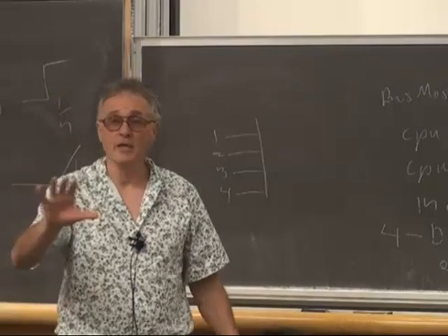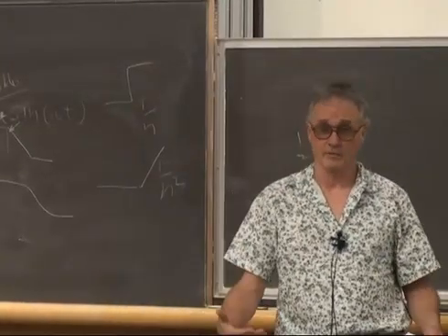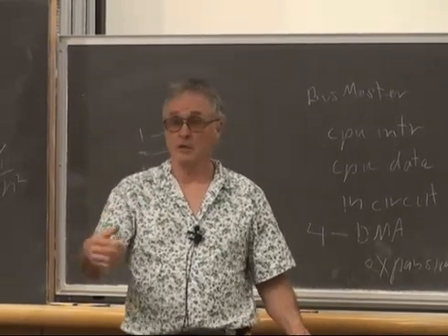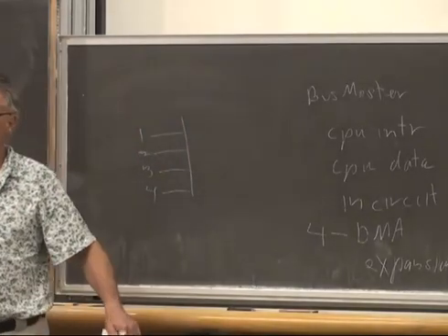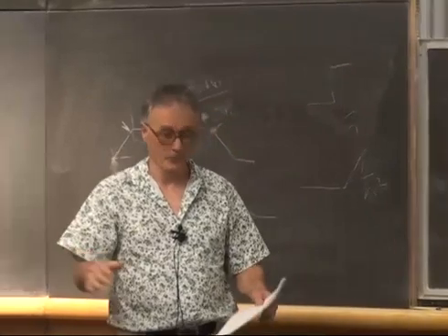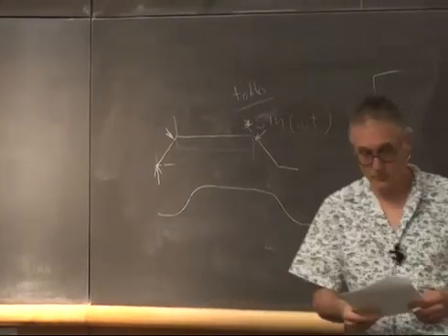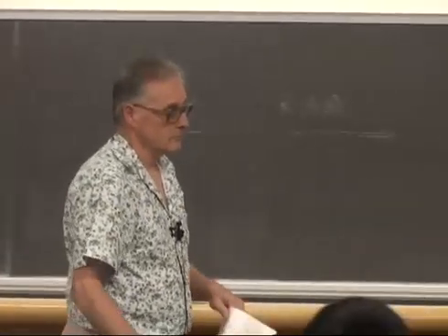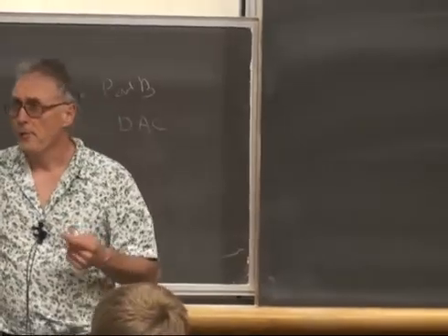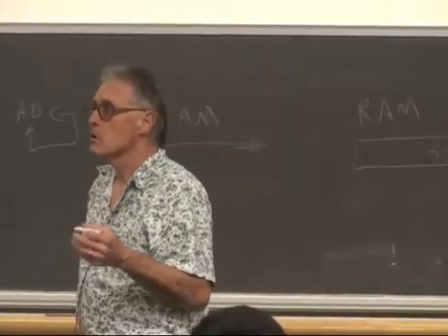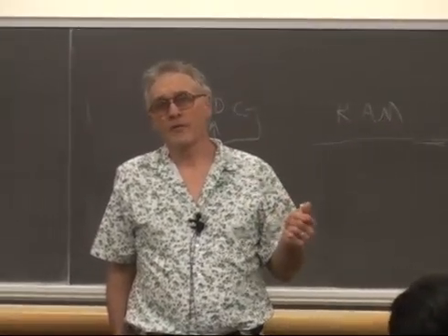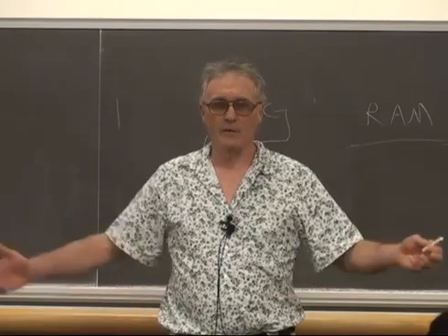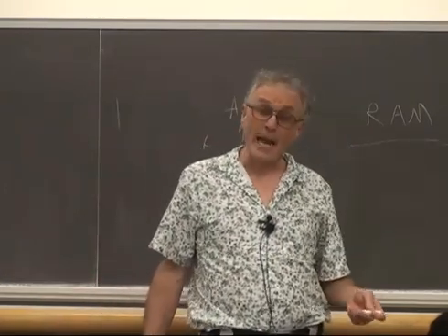So let me emphasize again, you set up the DMA using the CPU, obviously. There's a whole bunch of registers you have to set up. Then you arm the system. You say send data on an event, or just start. You arm the system, and then you go away and it does whatever it wants to do. So it is completely independent of the CPU. I don't believe I've ever played with an architecture before, except for System 360, which was big iron that had DMA channels, and it's pretty handy.